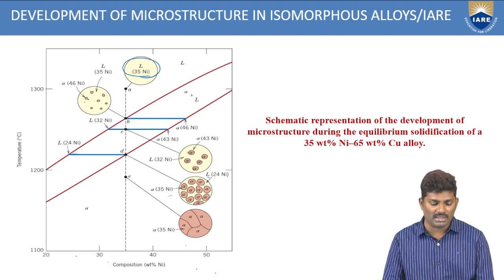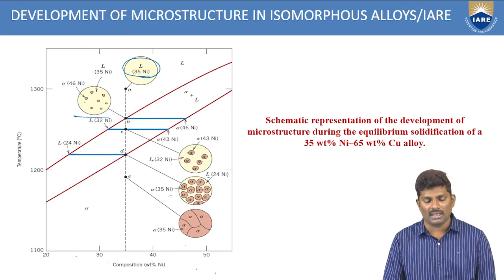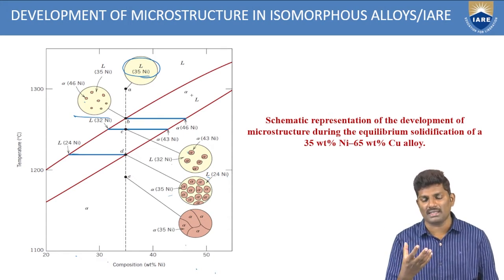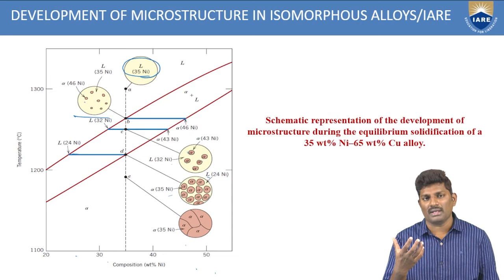If you compare the phase diagram or the microstructure, you can see there is a lot of difference. Some solid particles are being formed. By drawing the tie line, and from those tie lines drawing the perpendiculars, you will get the total composition. So this is another microstructure at point B. The point C is also lying along the two phases, that's why there is an increase in the solid nature. The size of the solid particles is increasing at point C by reducing the temperature.